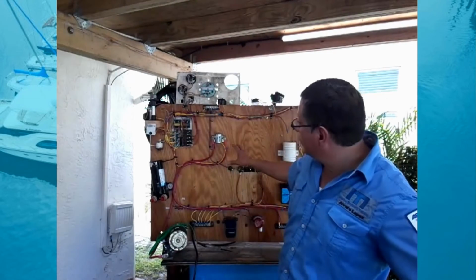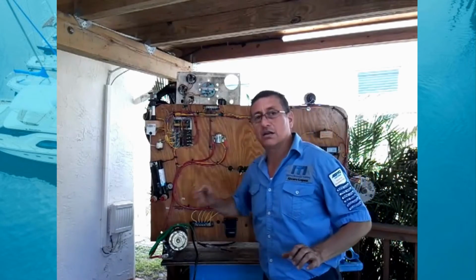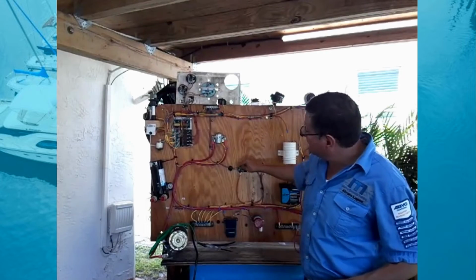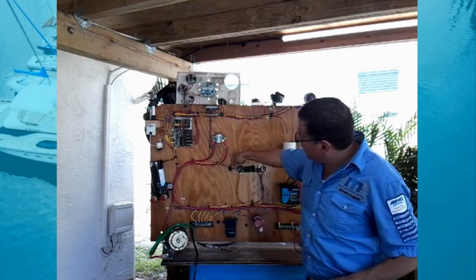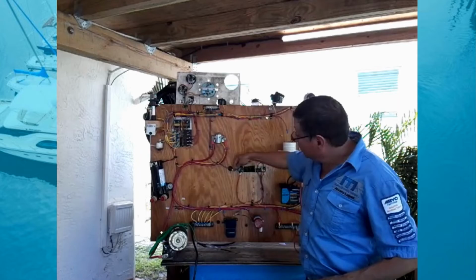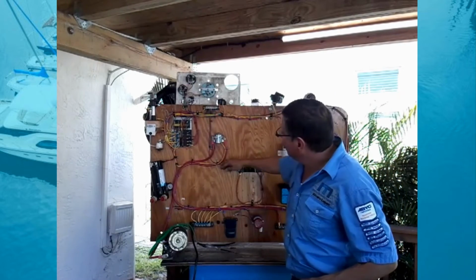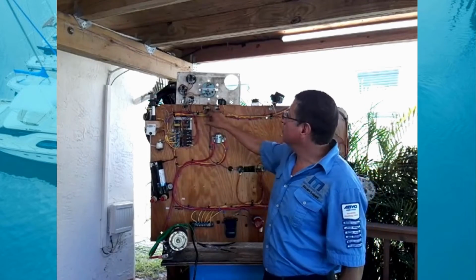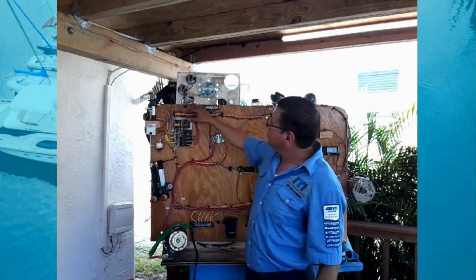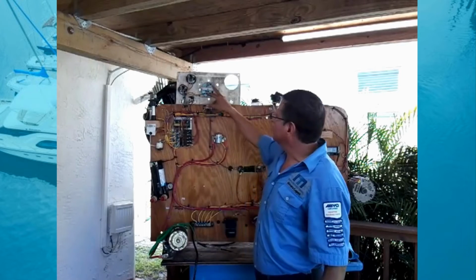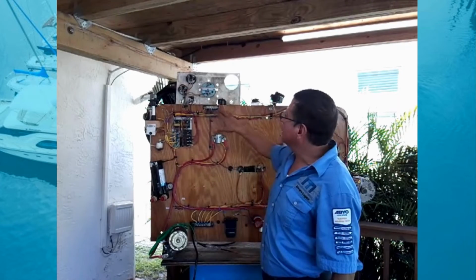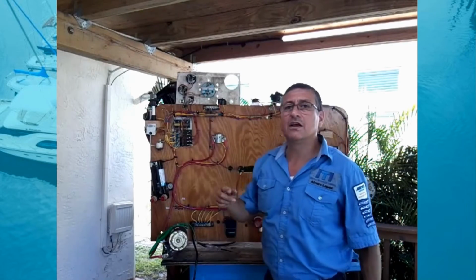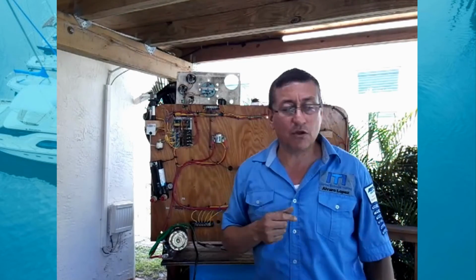This is the installation of the crank relay and the start solenoid. You remember when I explained to you that when you activate ignition, with the ignition cable, the purple cable, you activate this relay, but also you activate an ignition bus bar. From the ignition bus bar, you activate the oil pressure gauge, temperature sensor, tachometer, hour meter, hundreds of equipment, and also you send signals for the harness of the motor.